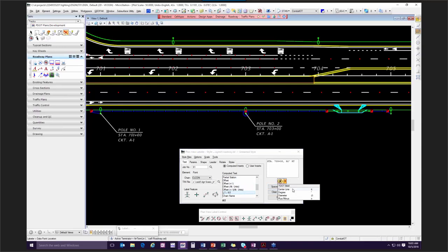All right, then I'm going to put in a space. There is a symbol in here for a center line. However, notice it comes in and it gives you this crazy font information here, 8452. If I was in the labeler, like the place text tool, this would work. But in the Geopak labeler, this is an old tool and it doesn't work. What I want to type in here, I'm trying to get the center line symbol, and I happen to know it's 161. So it is the backslash and then the character number.